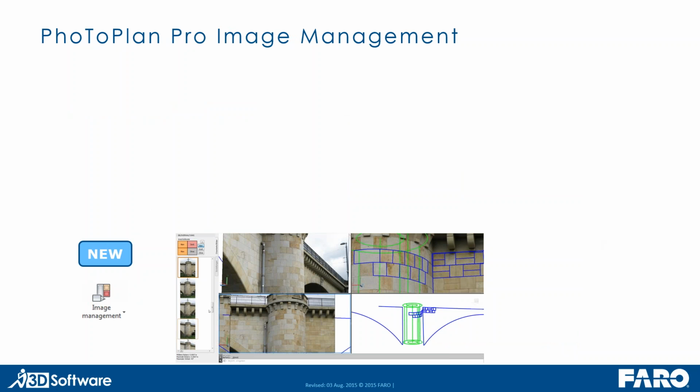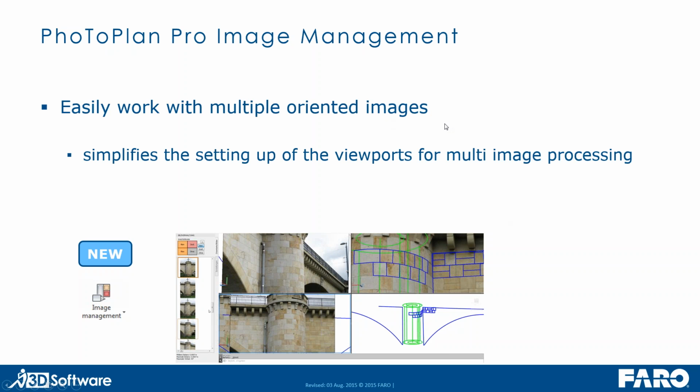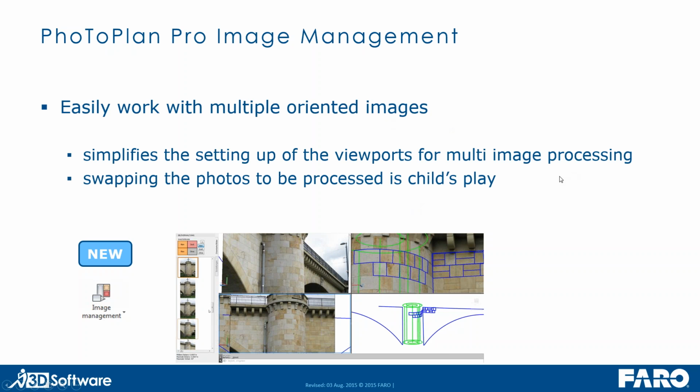So in order to make this photogrammetry tool much more comfortable, we added the new image management in PhotoPlan 16.5, and this will help you to easily work with multiple oriented images, and it also simplifies the setting up of viewports for the image processing, as well as makes swapping the photographs in the viewports to be processed a child's play.